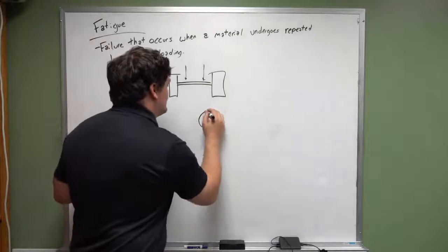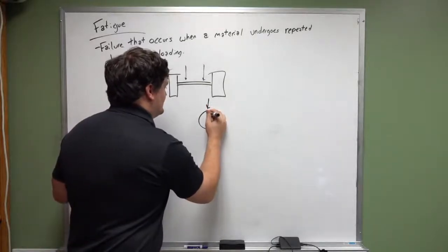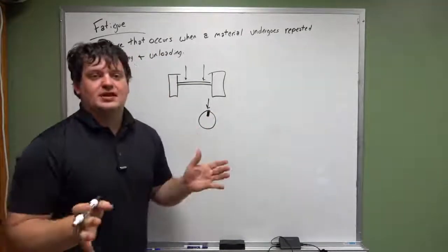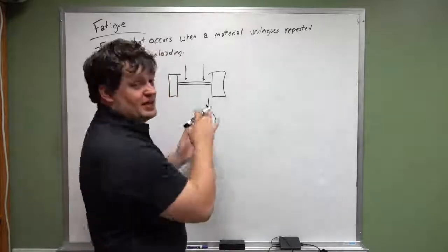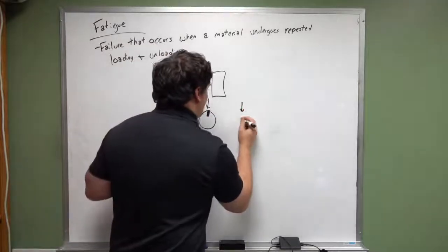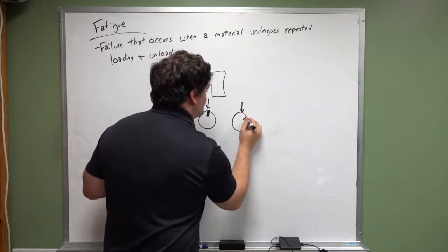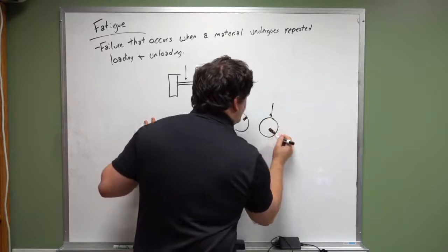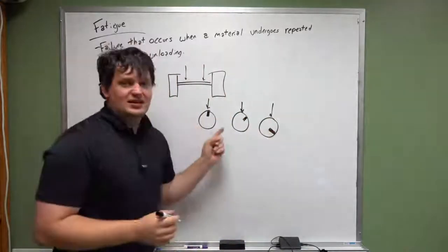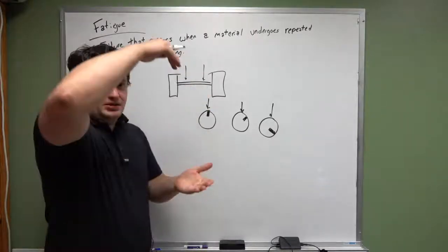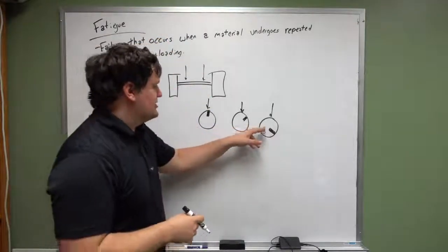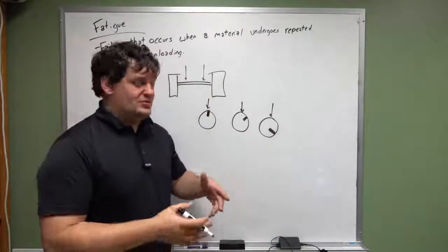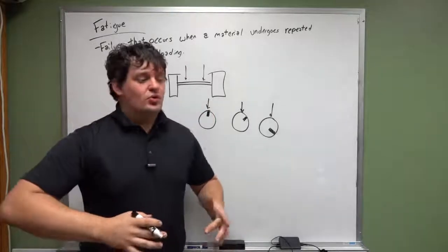And when it acts on this axle, the issue is this is a constant downward load. But the axle itself, let's say I've got a black mark here that identifies some point in the axle rotation. At this point here, that black mark is pointing upward. However, this force stays downward as this axle continues to turn. And what you have is that at its peak, this black mark will be in compression. Here on its side, it'll be in shear. When it's on its bottom, it may be in tension because of the bending load that's going on it.